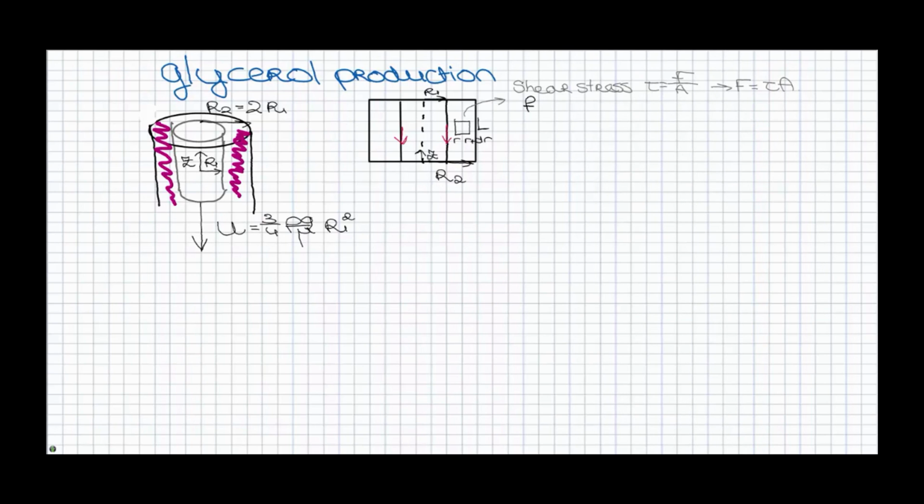So, setting up the force balance over the small part gives this equation. Outer surface of the cylinder times the shear stress at that specific point, so at r. And because the shear stress in the z direction in the surface with radius r has the smallest coordinate, it's positive. So in the force balance, the shear stress at point r plus dr is negative.